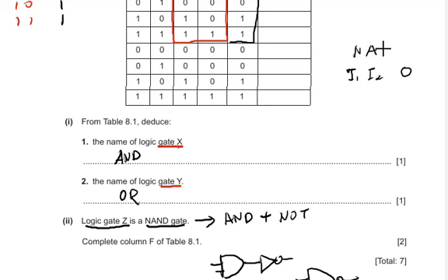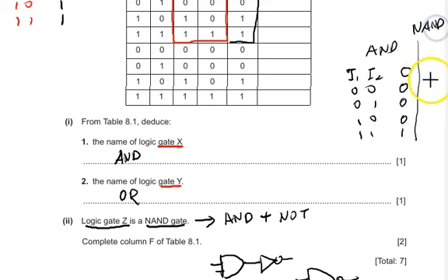We try to do it for the AND gate first. AND gate, so we have 0 0 0 1, with 1 0 here and 1 1 here. So if it is an AND gate, it should be 0 0 0 1. All right. So here is a NAND gate, which is 1 1 1 0. So this is the answer for the NAND gate.